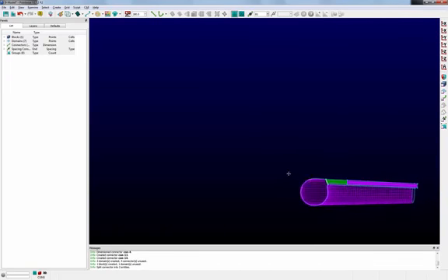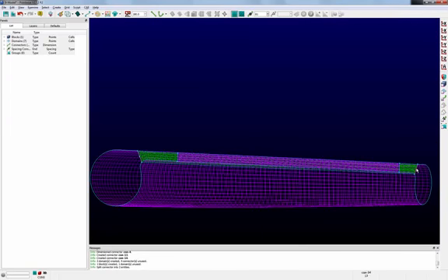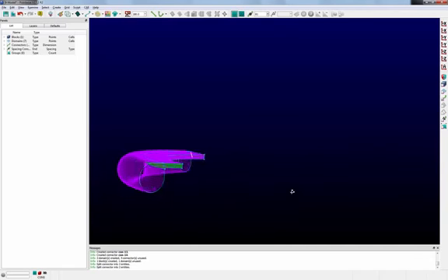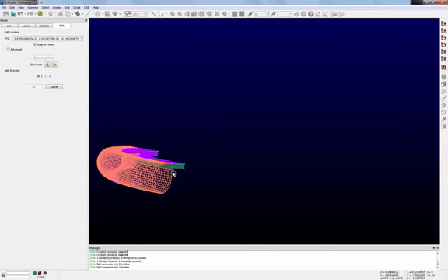The other thing I'm going to do, well, I'll repeat it on the other end for one, so Control Q to bring that back up, split it at 50, and click OK. The other thing I'm going to do is go ahead and split the outer part into our 4 pieces for that OH topology.